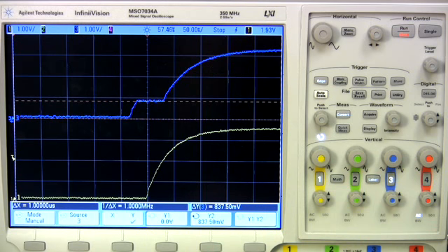This demonstrates the Si8405 anti-latch circuit in action. Relative to typical I2C clock frequency of 400 kilohertz, the approximate 30 nanosecond delay in the B side transition and added 30 nanosecond delay until this propagates back to the A side is very acceptable.